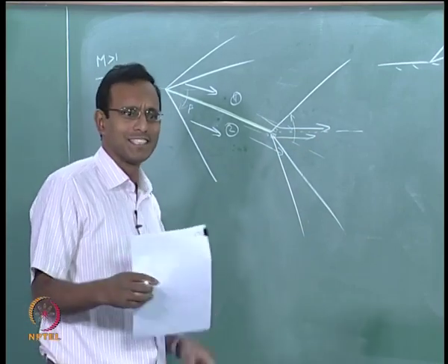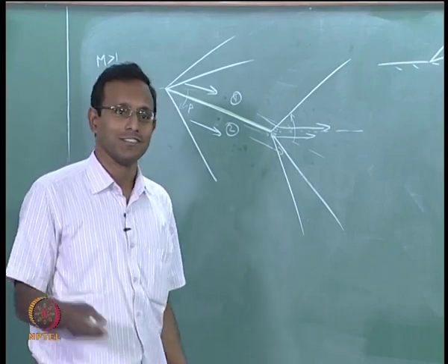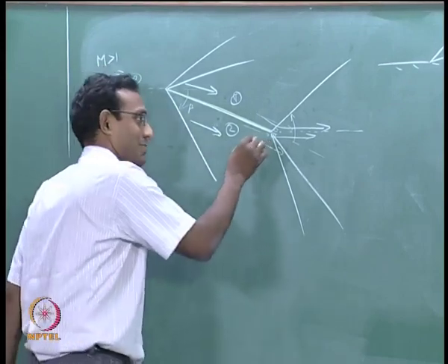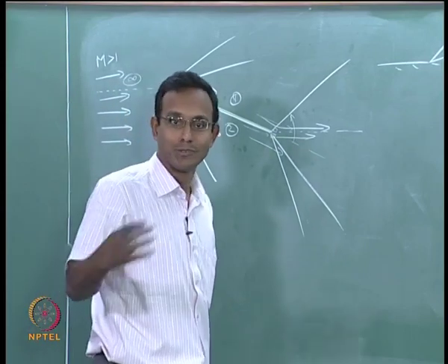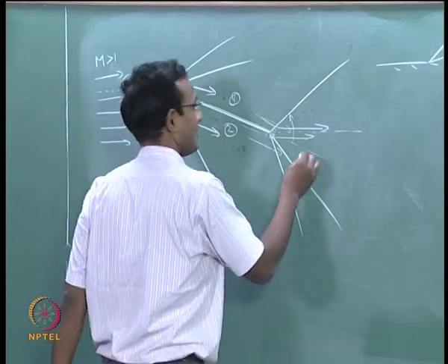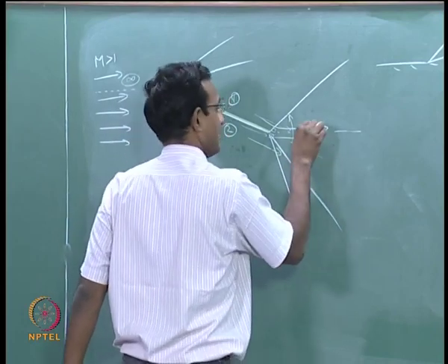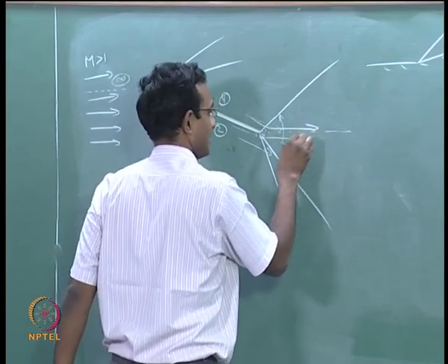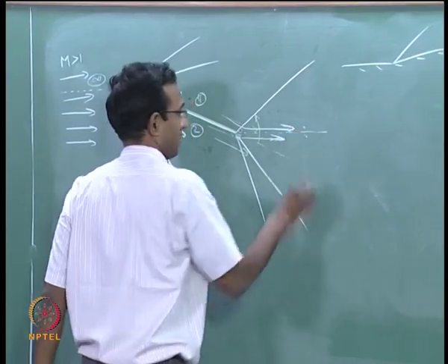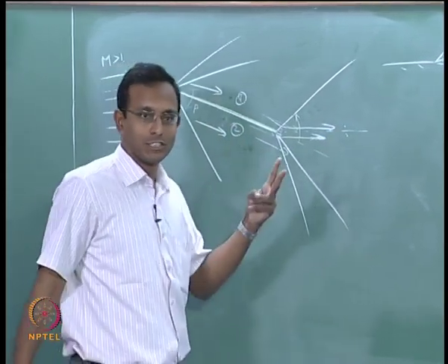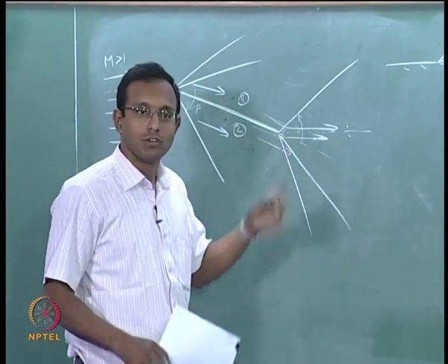I told you already in gas dynamics always there are two conditions. What are the two conditions? One is the velocity vector direction, other is the pressure. We keep on repeating this all through this. Okay? We will see how it goes. We have to make sure that these two vector directions are the same, at the same time these two pressures are the same. Two conditions, two constants I have to get.